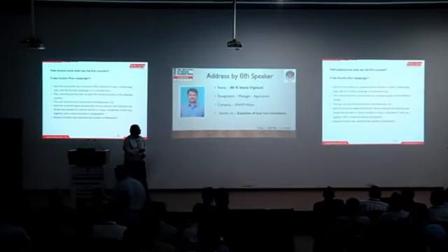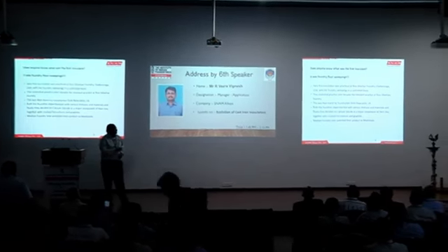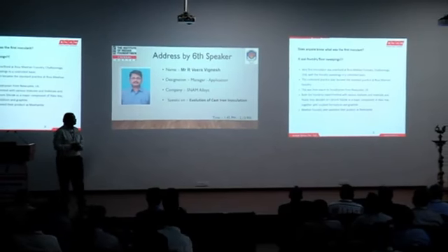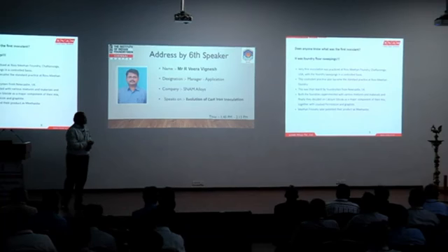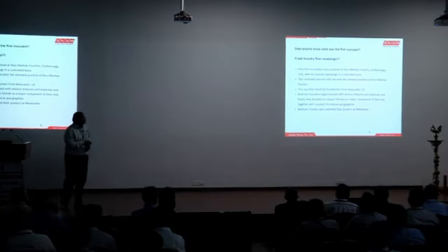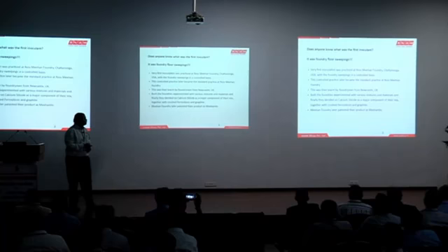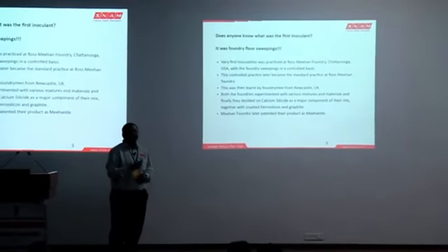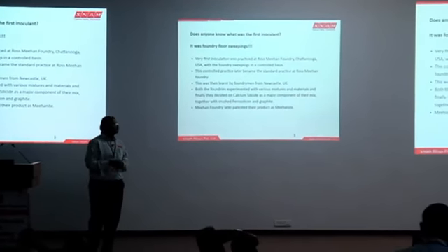This happened in a foundry called Ross Meehan Foundry in USA. When they analyzed these castings, the results had come out very good, and they started analyzing what change could have happened. They found calcium silicide as a major component of their mix, which the foundry sweepings contained. So they later patented the technology, and they call that Meehanite iron. That is, iron produced with that particular mixture giving good results is called Meehanite iron.